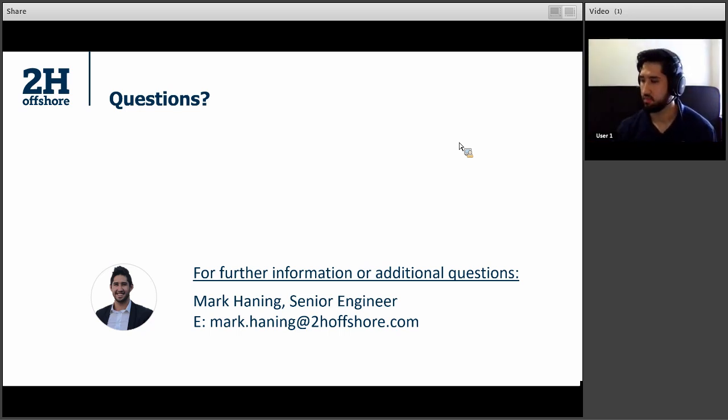Okay, thanks, Mark. Another one that came in: how do we consider MLS in FE modelling? I guess the easiest way to think of an MLS is just something that engages at the seabed and creates a boundary condition. That's the way we have used it. There are different types of MLS, so that's also something to be aware of. It's not always a hard and fast rule, so it's really good to engage with the operator or the vendor of that particular MLS, but typically speaking, we just use a boundary condition in FEA.